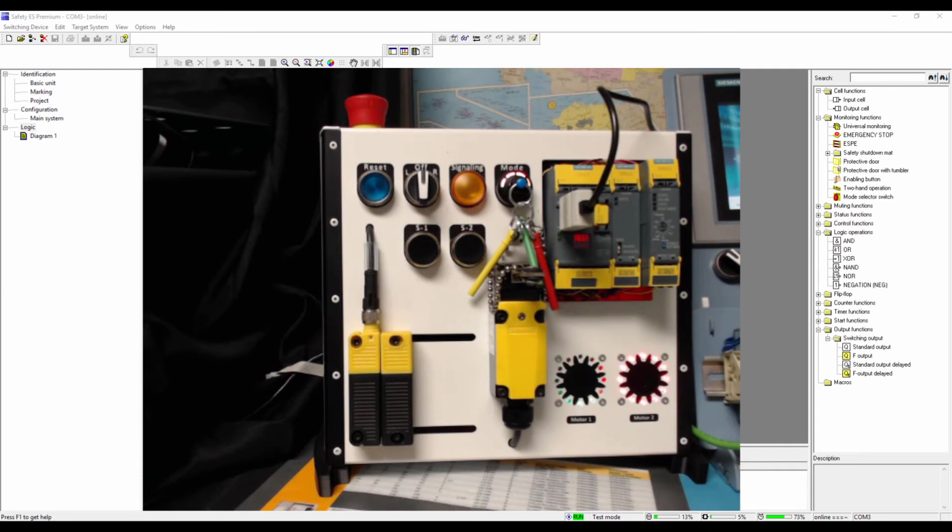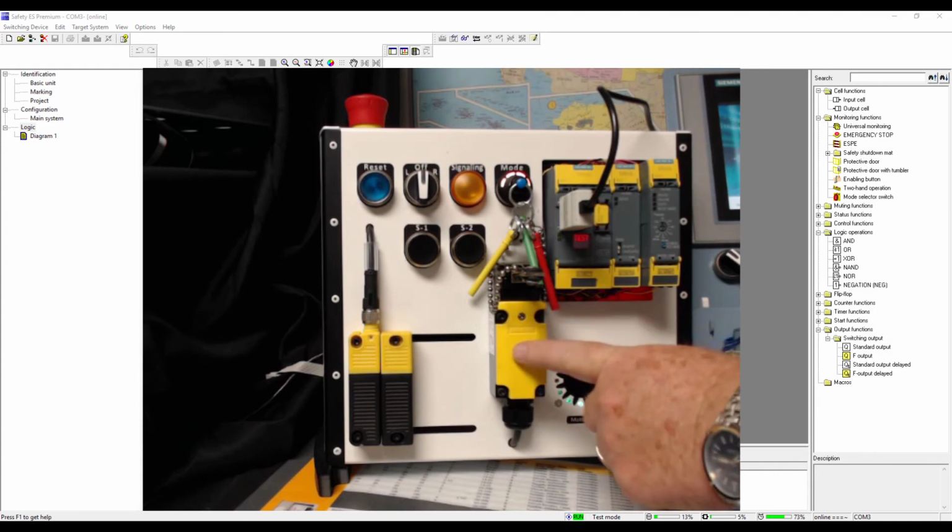So now we're going to move on to exercise 3, where we're going to add a second zone output. And that's really the strength of a programmable safety relay, is to do multiple zones on your output side. It's nice to be able to change the software easily for a single zone, but when you have multiple zones, that is really the strength of the 3SK2 series. So now we'll go to exercise 3, where we're going to add the interlock switch.